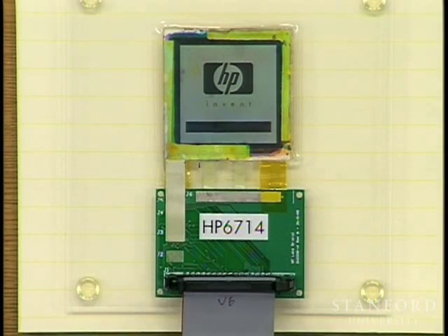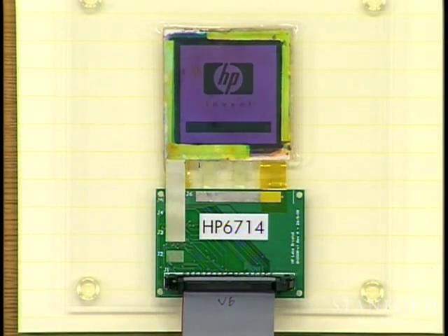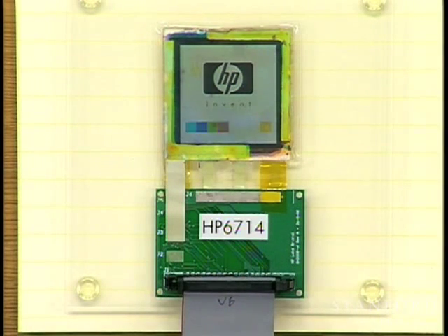Color, lots of color. So basically the purpose of this demonstrator is to show the black and white points of this are pretty much the same as e-ink. It's not using an electrophoretic medium. It's a different electro-optic effect that we're working with. But what we're adding to that is color that's reasonable. And the other thing that we're adding to it is actually near video rate. So those are two important things.